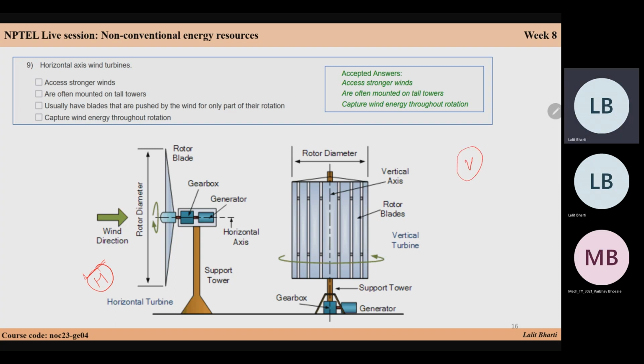In this, these are push type wind turbines where your blades are not sharp, but you have a very large surface area, or a large contact area with air. Due to the large contact area, you will have lower velocity, lower speeds, but higher torque. By this advantage, you can make them in smaller dimensions.